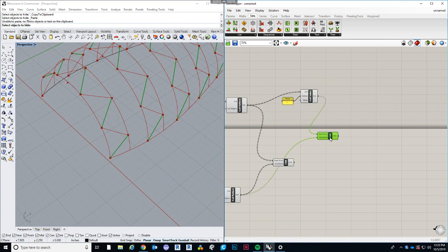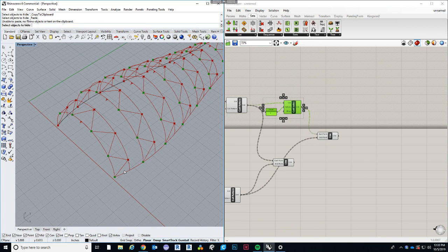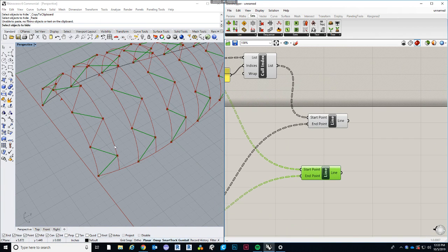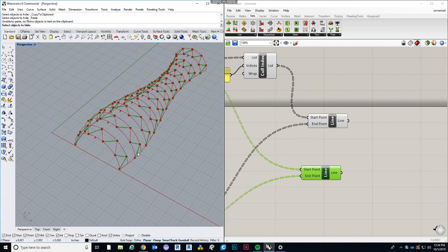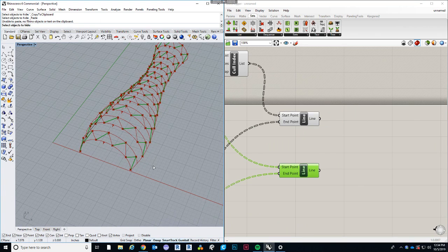And one thing we got to be careful of when we're creating these lines and subsequently the surfaces that we'll create is that we want to make sure that there are no recurrent curves in the script. And what I mean by that is, see how in this array of curves you get this extra one down here, and when we select the other line it's still highlighted. That will be what we call a recurrent piece of data. It is a duplicate essentially, and we want to be able to remove those duplicates so we don't get multiple surfaces or different lengths of lists when we get down the line. You don't want overlapping stuff. We want it to be as clean as possible.